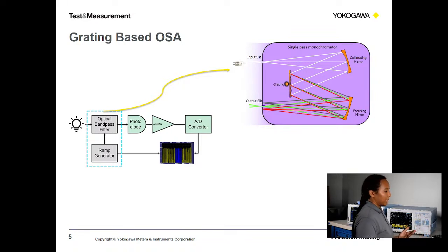So this mirror of prisms splits the light, then it hits another mirror, and all those split colors are then directed toward an optical slit. And that slit, depending on where you are exactly measuring, moves around or widens and retracts, gets smaller to read exactly what that optical signal is.